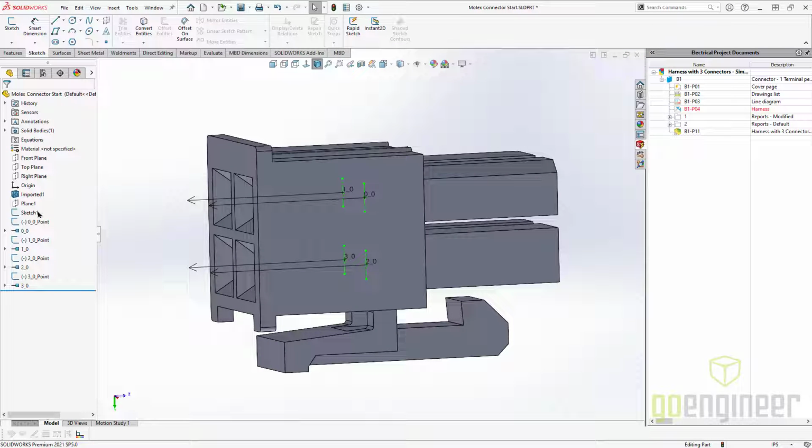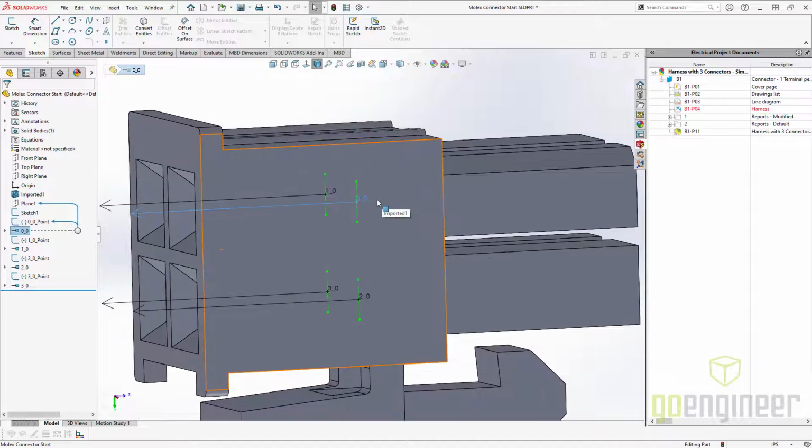So what it did is it took my original sketch and then it made copies of each sketch point into its own separate sketch. If you had a single sketch with a single point, then it just renames your own sketch. So if it sees multiple other entities in that, it has to make a copy of that sketch there. And then it creates a connection point or a C point that is specifically named.